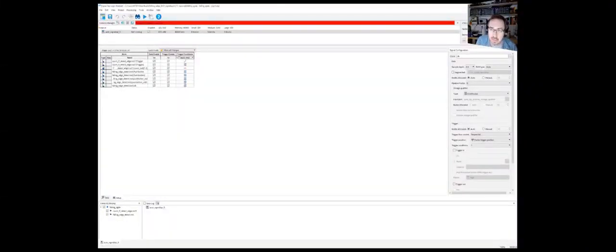Right, so let's program the device. And the important thing about this Signal Tap design is the trigger, as you can see here, is on the rising edge of the signal called trigger. And that's at the center of the waveform window. So when I push the button, that should trigger Signal Tap, and we should see all of the waveforms around that trigger. It's exactly the same as how a normal oscilloscope trigger works.